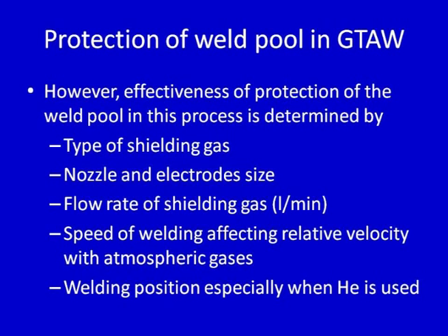So, in the downhand welding position, the helium tends to move up, while in the case of the overhead welding position, movement of the helium in the upward direction is helpful. So, if we see in the downhand position, like in the horizontal welding and in the flat position welding, the higher flow rate of the helium is required for protection of the weld pool,